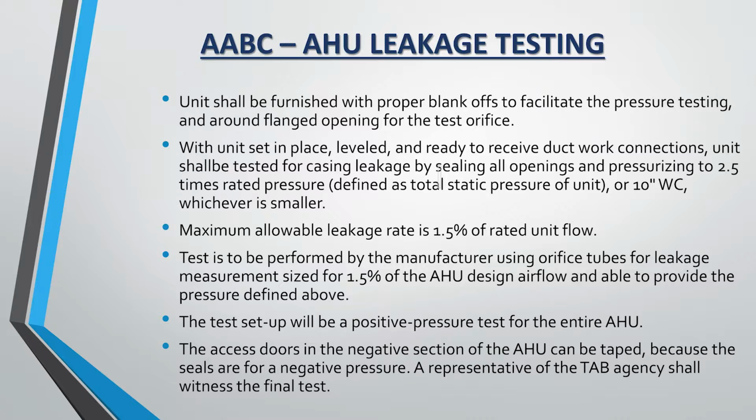With the unit set in place, leveled, ready to receive ductwork connections, units shall be tested for casing leaks, all openings, and pressurized to 2.5 times rated pressure, defined as static pressure of a unit, or 10 inches, whichever is smaller. So, with that being said,